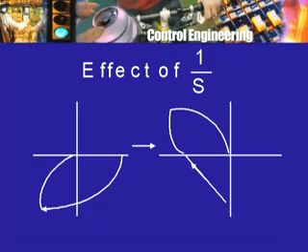and because of this, from this we went to this. Now, as a result, this plot is crossing the negative real axis, that is, at some frequency the phase shift is becoming 180 degrees, and therefore we can be in the danger zone, because if the gain corresponding to this is 1 or more, then the point minus 1 plus j 0 may turn out to be inside the overall contour gamma prime. Of course, it is too soon to say anything, because I have to complete the whole contour, then only I can draw any conclusions. There may be poles of the transfer function GH in the right half plane, so I have to take care of all those factors.